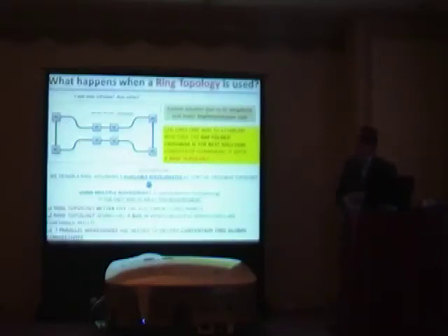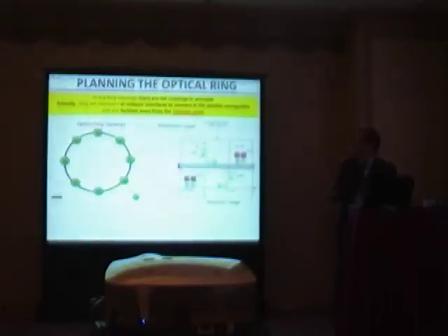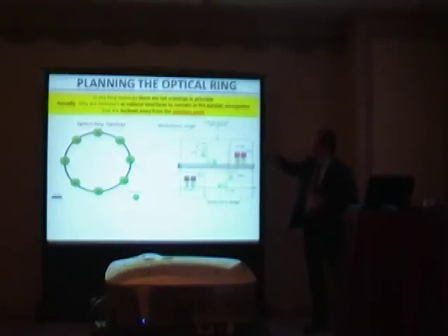Notice that the ring topology better maps our placement constraints, and it also works like a bus, which includes multiple waveguides. Here we have 7 waveguides to satisfy all communication scenarios, all global connectivity. But in the ring topology, there is a problem. In principle, in any ring topology, there are no crossings. But actually, they are localized at the initiator interfaces.